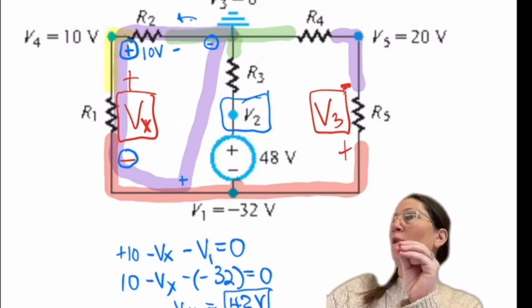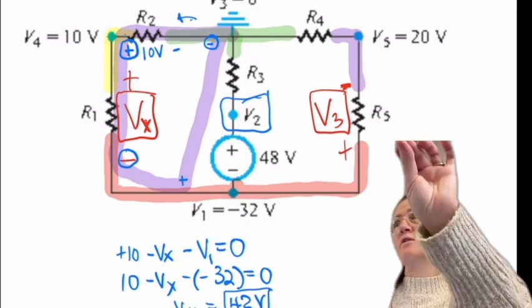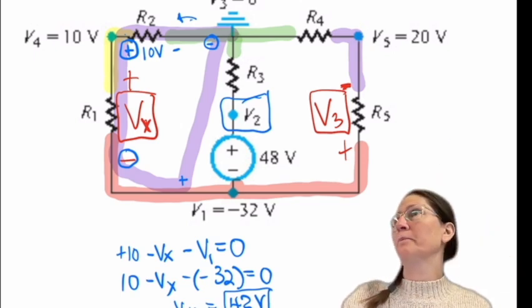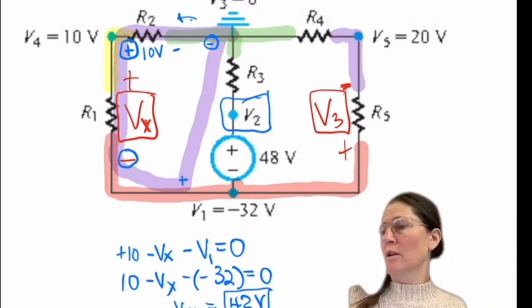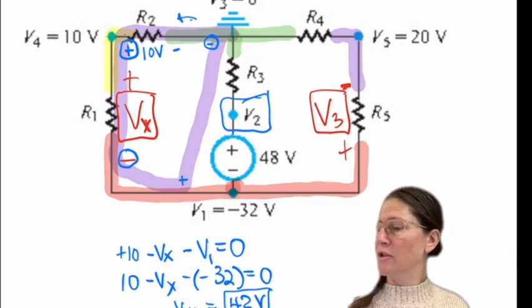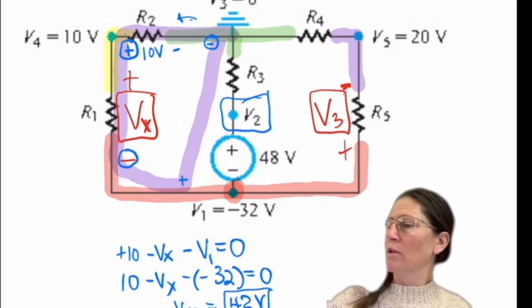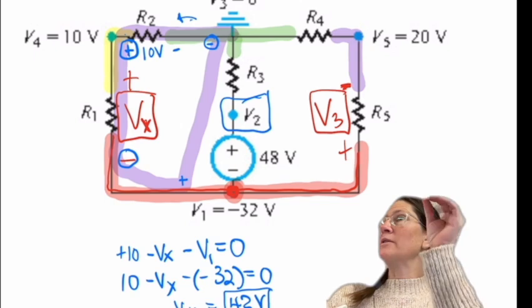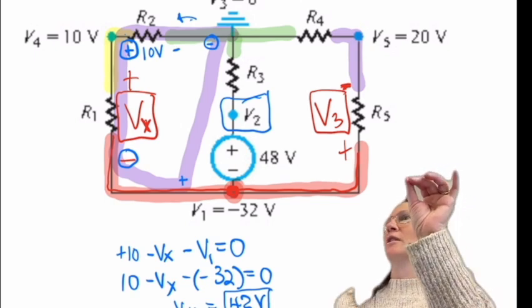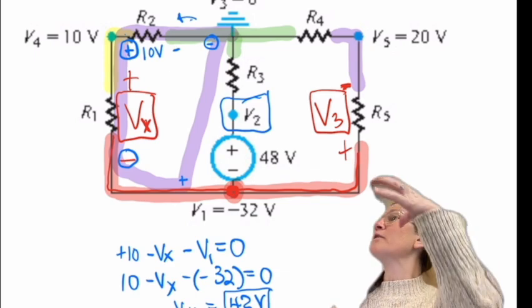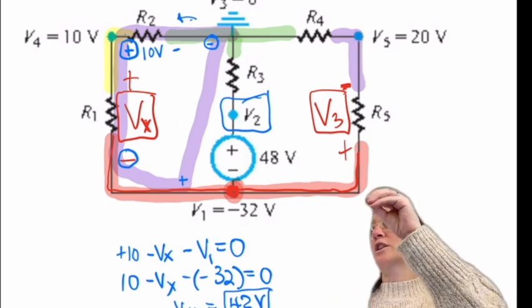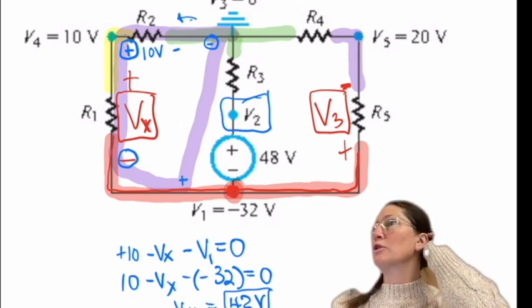So whenever you see that node, it means there's a connection from there to ground through a separate device, like a multimeter. Anywhere on a wire, anywhere in a circuit, if I write a voltage, that means from that point to ground is that voltage. As if I'd put a battery there, but it's not going to conduct current through there, but it will have a voltage.